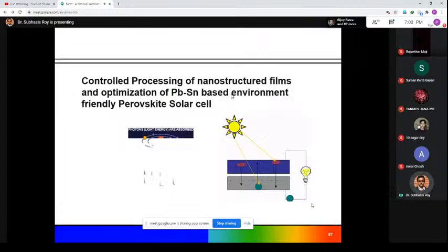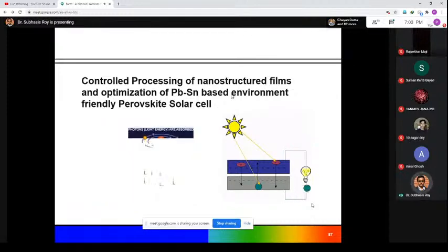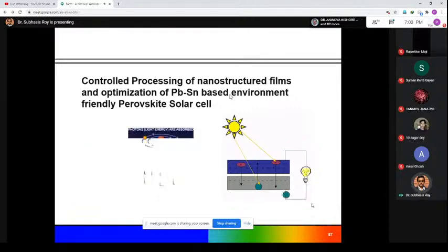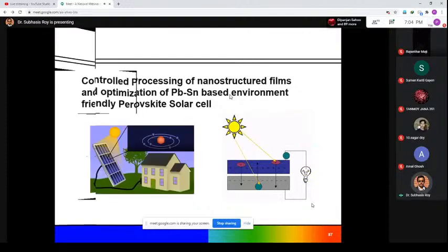So this is the second part, where clean hydrogen generation from water splitting is available by applying the perovskite nanostructure material. Now the third part I am coming to, the solar cells. We fabricate solar thin films using nanoparticles, particularly perovskite materials. We replace the lead, which is a hazardous material in this case, with tin, which is very environmentally friendly.